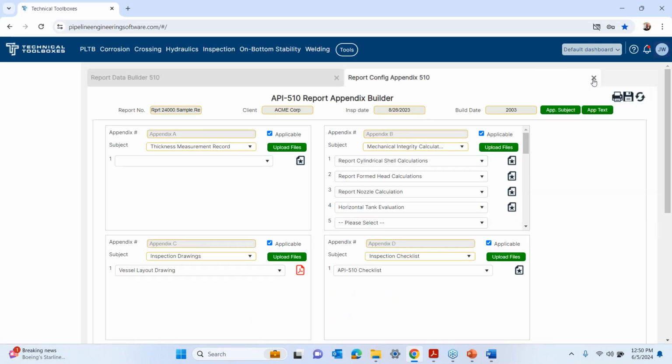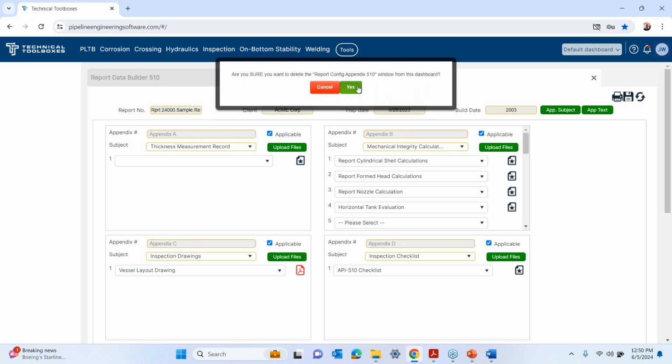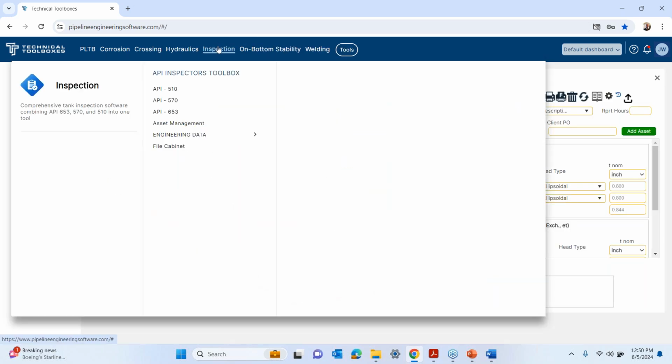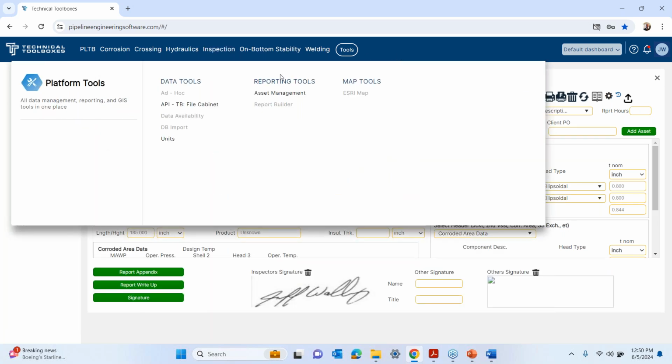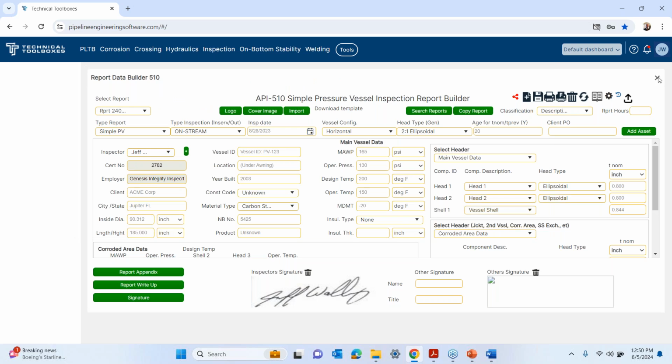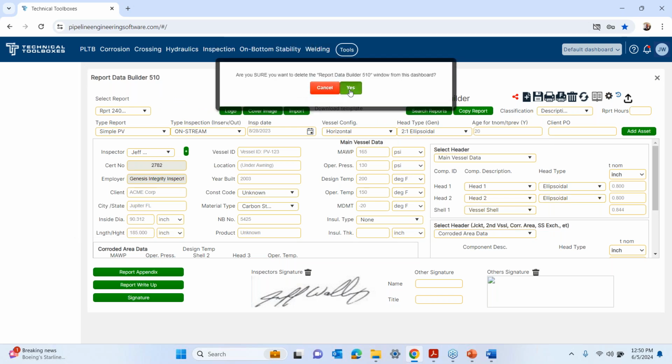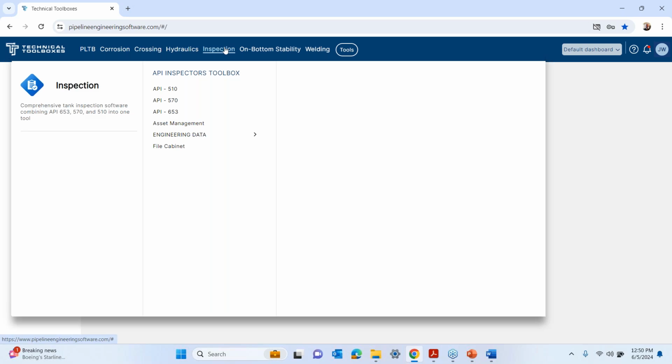What if you find areas in the piping where the actual thickness is below the practical T-mins in your program? Okay, well, obviously you're talking about API 570. Those practical T-mins are given in 570, and each and every organization has to determine their own.